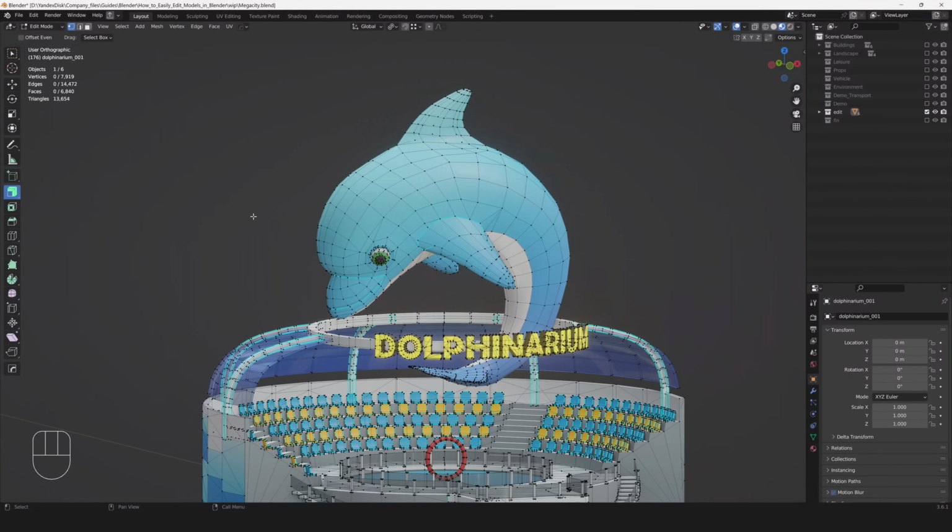But it's not really always the case, because sometimes you need to select something that is inside of your object or after this object and you cannot rotate your camera, and in this case you can just select it with X-ray mode. X-ray transparency mode means that you can select anything behind your front surface.